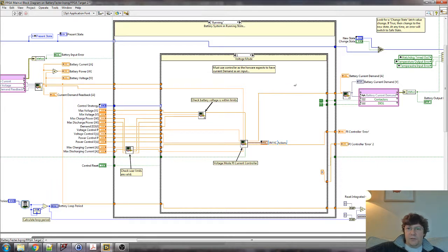So if your battery is only 30% SOC and you ask it to be raised to 14.8 volts, the current will be whatever you can drive in. And that might, of course, kill your power electronics or blow a fuse, but mostly the semiconductor devices will save the fuse, which is a shame because the fuse is pretty cheap, unlike the power FETs.